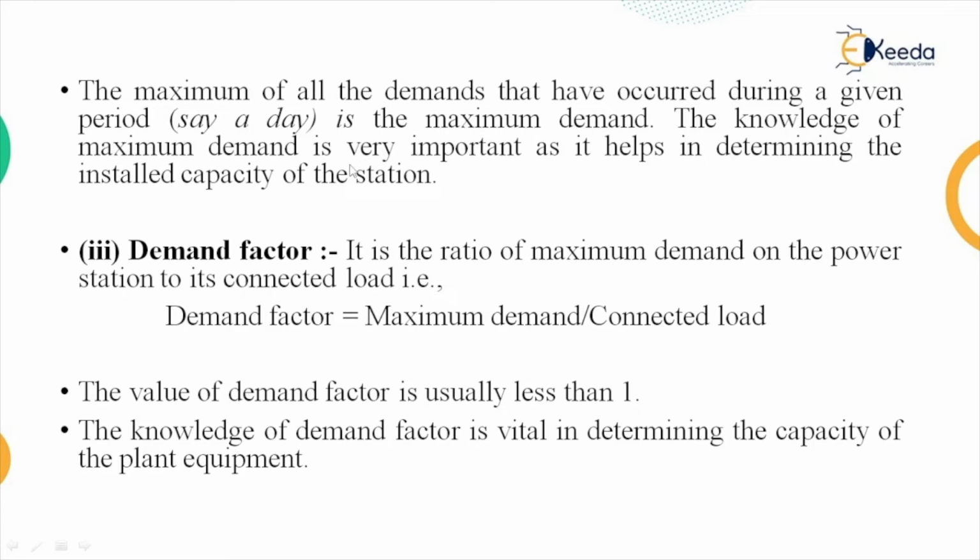The knowledge of maximum demand is very important as it helps in determining the installed capacity of the station, because from the maximum demand we can calculate the installed capacity.